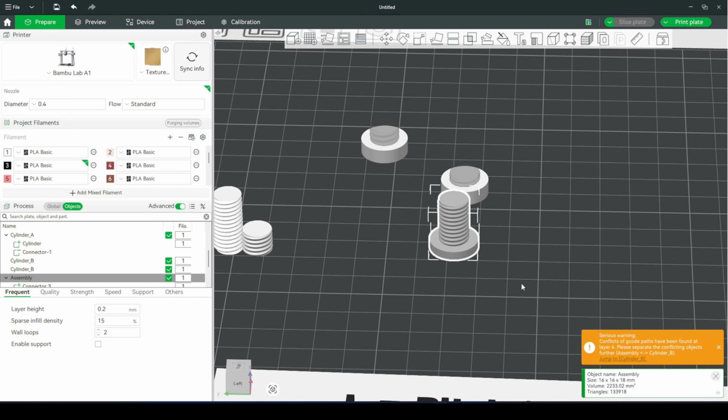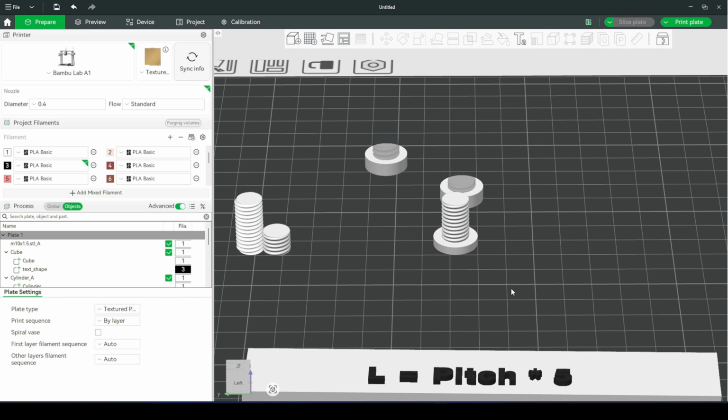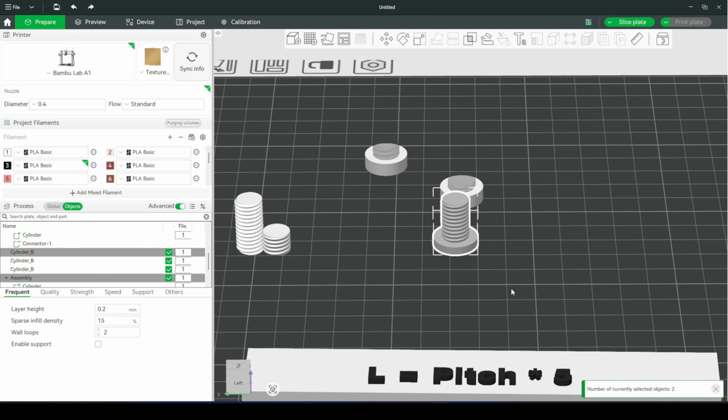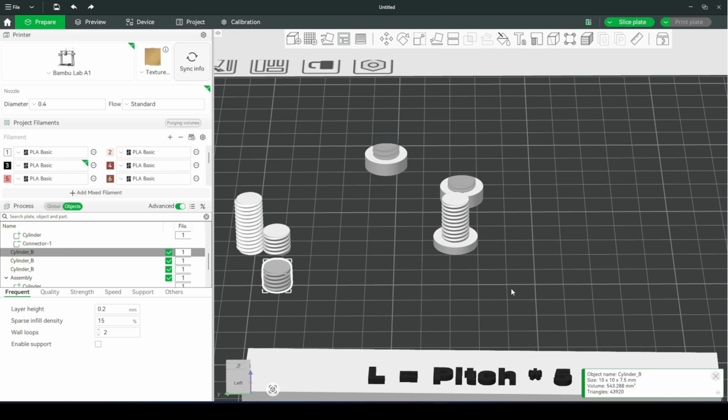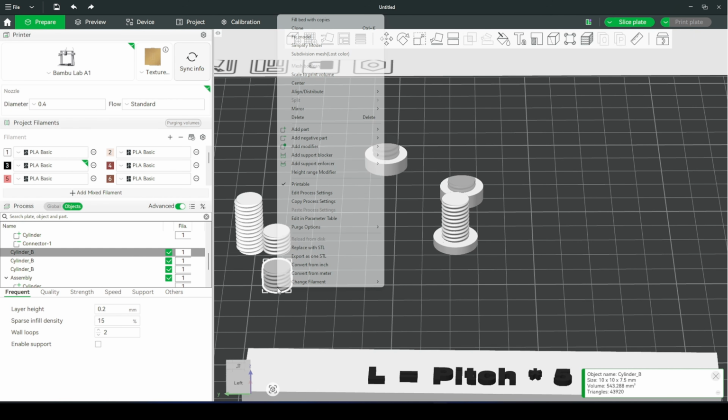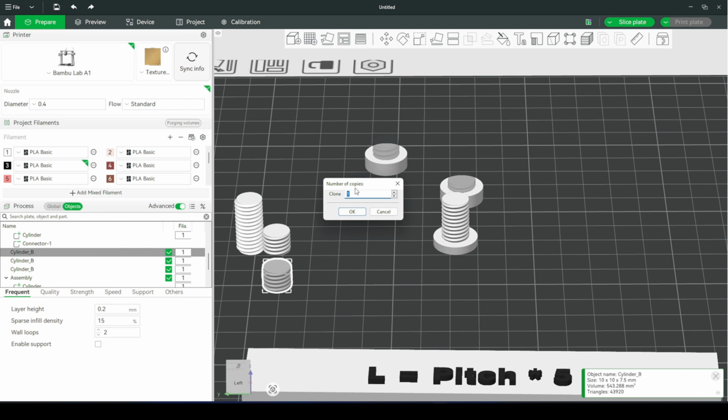Want to make it even longer? It's simple. Instead of cloning the thread just once, clone it 3 or 4 times. Just use the exact same move logic to stack them on top of each other. As you can see here, I cloned the headless thread 4 times.